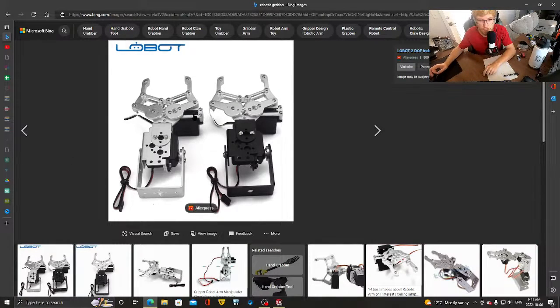So the idea is the same basic idea as this. We'll have two circles. The servo attaches to one of those circles. Those circles interface with a set of gears. We'll then have a 4-bar linkage of equal lengths on either side, so I can close and open nice and evenly. We want to have a nice flat face in the middle regardless of how wide the jaw is. And then we'll have just the jaws stick out, and that'll be the actual clamping mechanism.